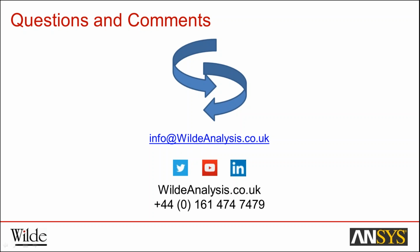Okay. Another question here. You looked at the deformed shape capability. Does that actually carry over the stresses when starting a new simulation? No, that doesn't carry over the stresses. It just carries over the deformed shape. But you can carry over stresses if you want to, using some additional APDL command snippets. So it definitely is doable inside Workbench if you do want to do it.